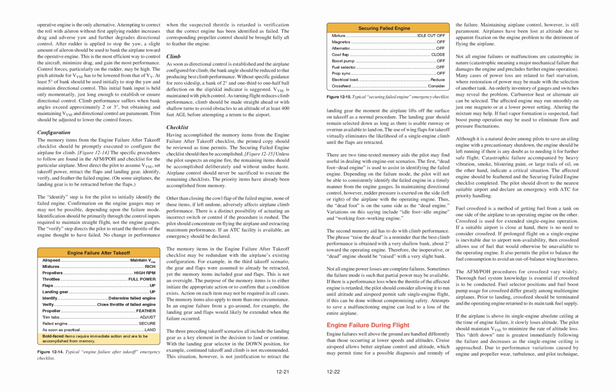There is a distinct possibility of actuating an incorrect switch or control if the procedure is rushed. The pilot should concentrate on flying the airplane and extracting maximum performance. If an ATC facility is available, an emergency should be declared.